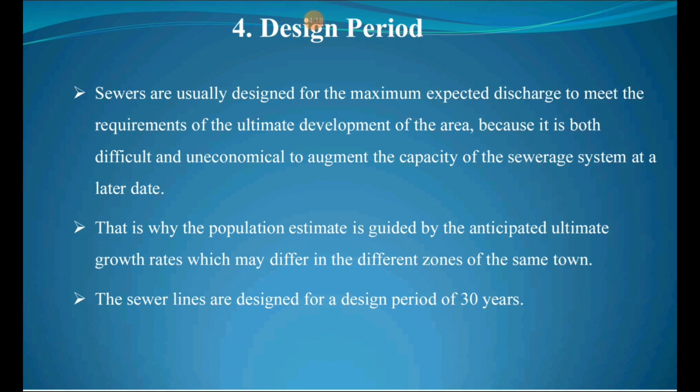The design period. Sewers are usually designed for the maximum expected discharge to meet the requirement of the ultimate development of the area, because it is both difficult and uneconomical to augment the capacity of the sewerage system at a later date. So perfect estimation is important. That's why the population estimate is guided by the anticipated ultimate growth rates, which may differ in the different zones of the same town.